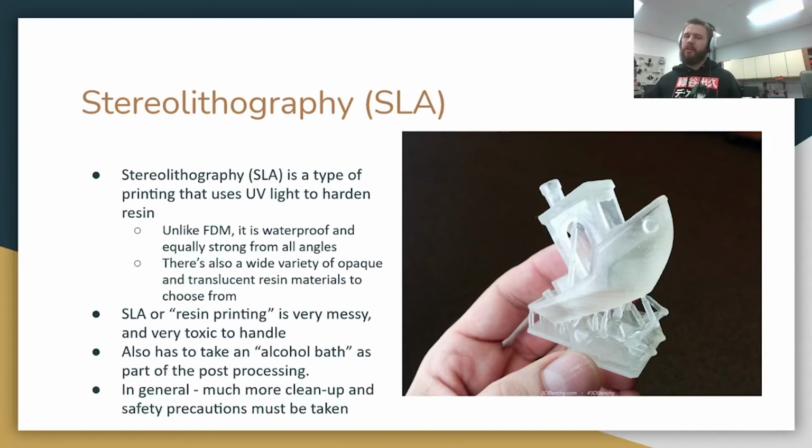So you're going to want to wear gloves when handling the inside of the 3D printer and when handling anything that you print, assuming that it hasn't had its UV bath. Speaking of UV bath, everything that you print using the resin printer has to go through multiple layers of post processing where you throw it in alcohol, let it sit for a bit, put it in a UV tank, let it sit in there for a bit, and depending on what you're using the 3D print for, it may have even more steps of post processing after the print.